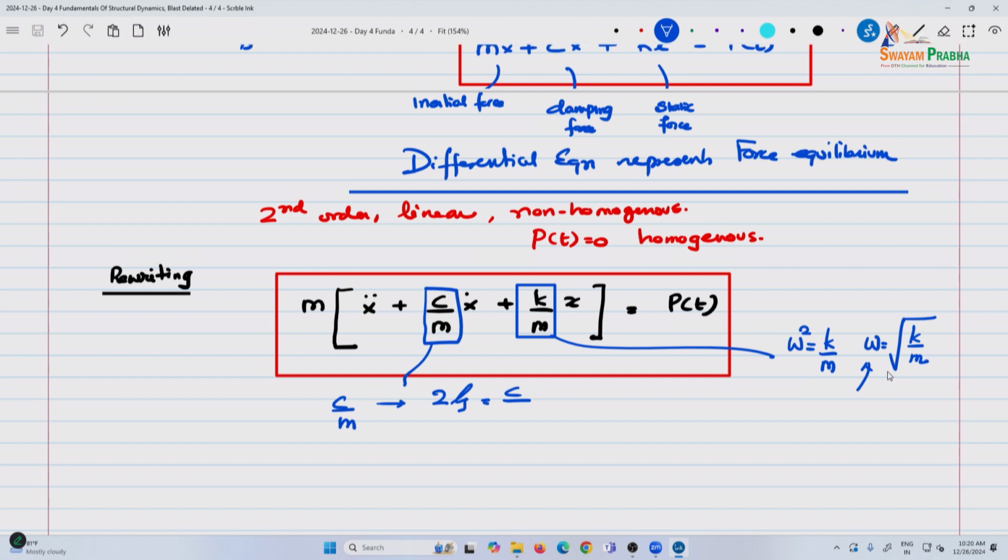So, more accurately, this is called the circular natural frequency, and it is represented as radians per second. That is why it is just equivalent to going in a circle. That motion from back to forth, one full cycle, is going in a circle. That is why it is a particle with omega so many radians per second, right? You think of it in that way.